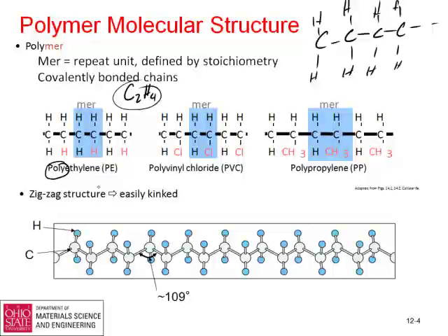There's a degree of polymerization, which means how many of these mers are part of that. Typically, with polymers, we're talking on the order of 100,000 to 1,000,000 of these mers, and that's what gives you a high polymer, a polymer with a high density sort of polyethylene material. So that's polyethylene, and these are all covalent bonds that you see in that picture.